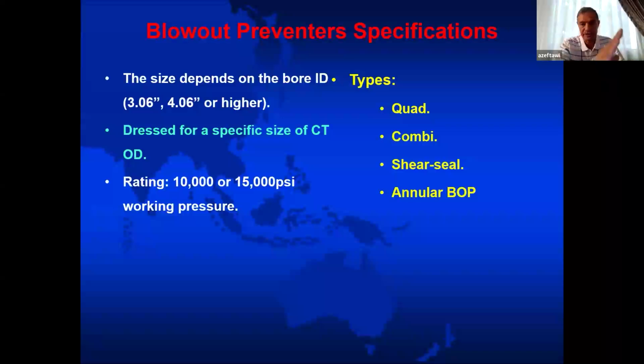But there is a fact now that you used a standard BOP in an H2S job. The job went perfectly. Now, what should you do with this BOP? Can you continue? Let us rig up, pressure test, and if it passes the test, then we continue. Or should you bring a third party and recertify the BOP? I mean, test it to 1.5 times its working pressure, and if it's okay, then we can continue, or what? This question, I need your answer.